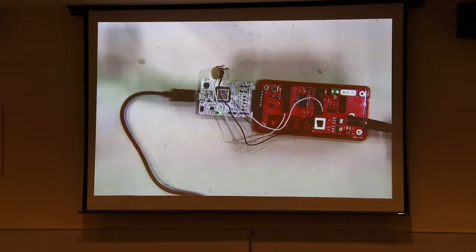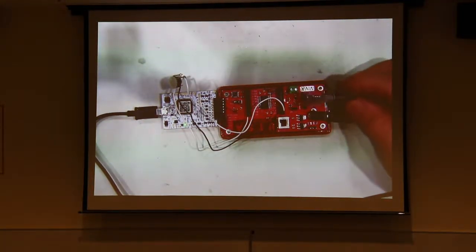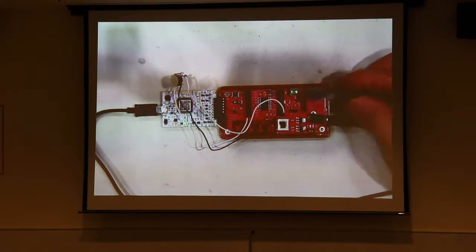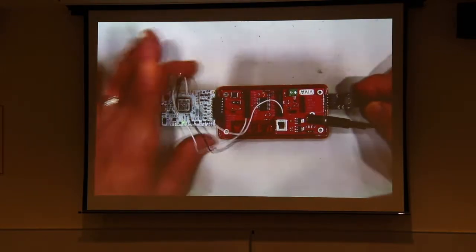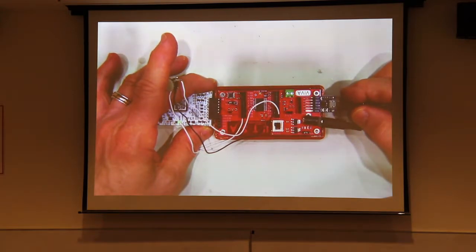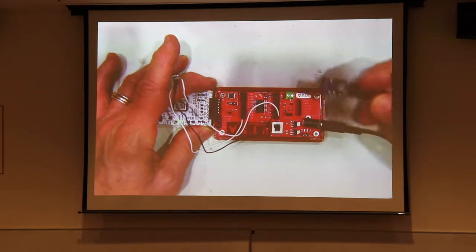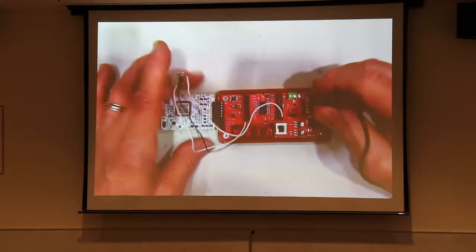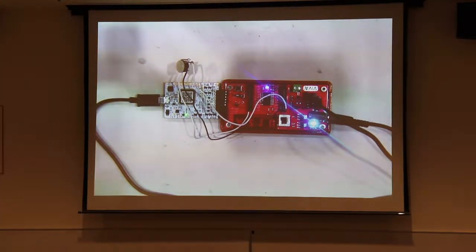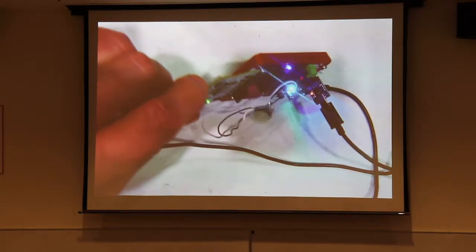Now, the way this is designed, if you want to, I'm willing to sell you one of these. You can buy it and just have it permanently mounted here. And you can actually power your board through this too. So if you compare the pin out here to the UART, you have to plug it in such a way that the pins line up, which actually is like this. But if you put right angle pins like this and they come out the top, you can put it on like this. Okay? And when it's sending data, you'll see the little red LED on it lights up, and it's actually flashing real bright, but it's flashing too fast, you can't really see it.